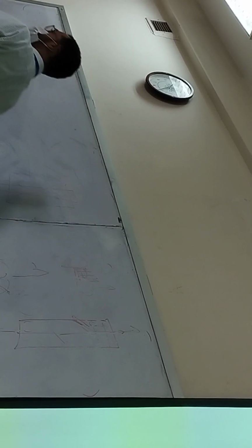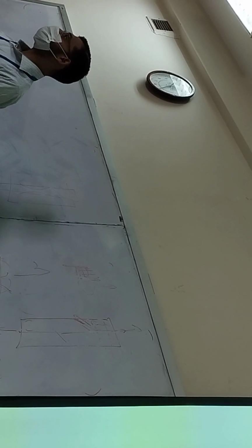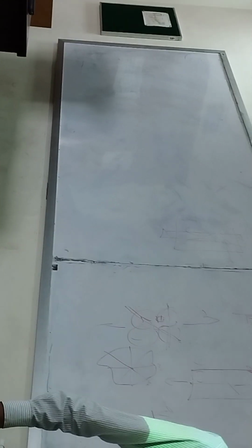If this is A1, A2, A3, the difference between A1 and A2 is going to be very less, around maybe not more than 20%. These kind of grains are going to be known as uniaxial grains, meaning they are more or less rounded in appearance. If they are elongated in a certain direction, like in this one, so the principal axis along the x-axis is longer as compared with along the y-axis.